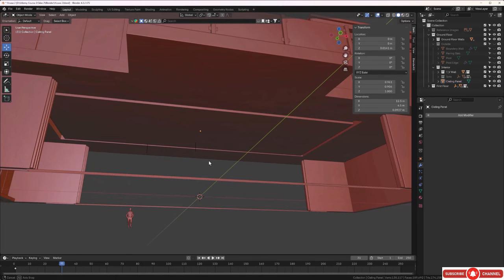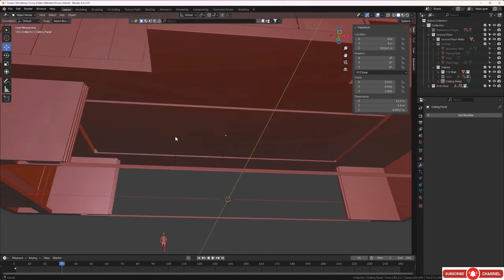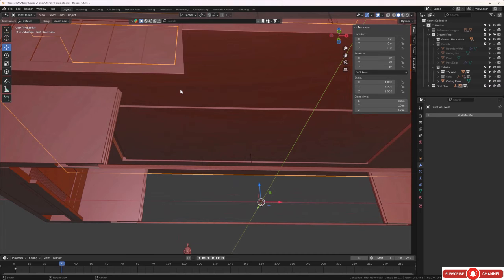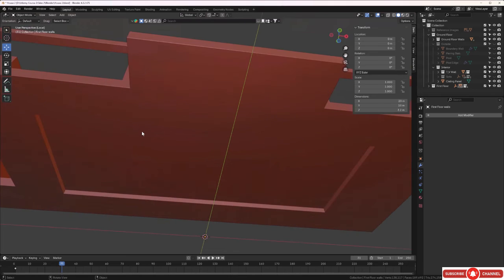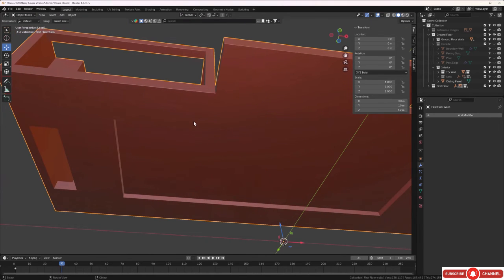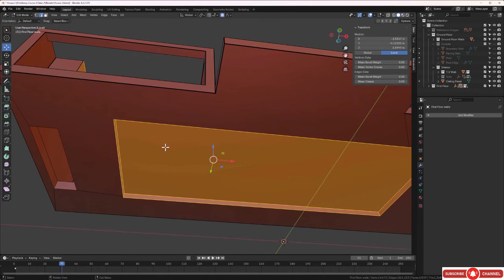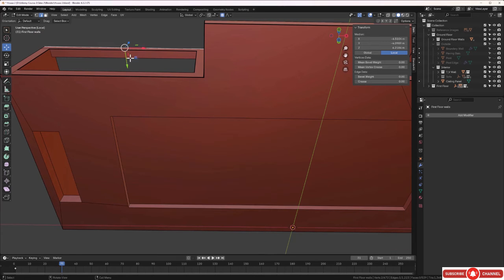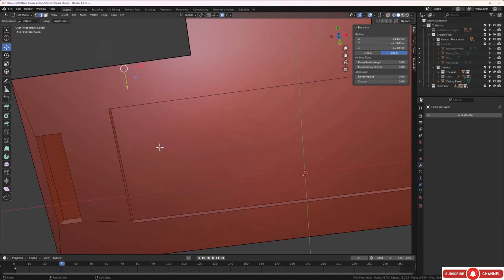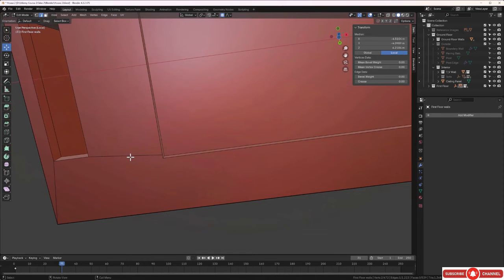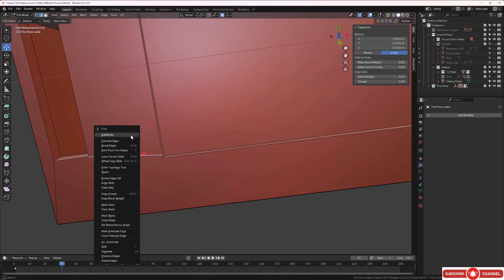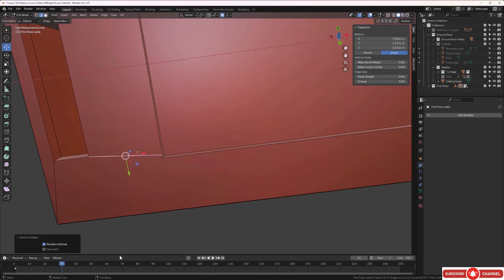Now that we've done that, maybe let's put some bevels on everything. So I think for now I'm just going to grab this and hit the / key to just isolate it. Let's tap into edit mode with it and make sure we've got edge selection on, which we have. And it's created some extra edges here with this Boolean. I don't think I can get rid of those. I think it's going to cause me issues, but I'll try dissolving it and see what happens.